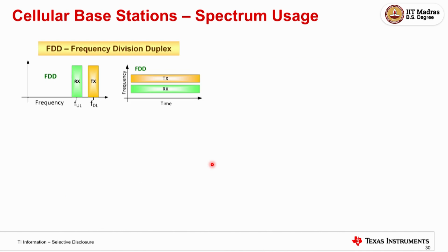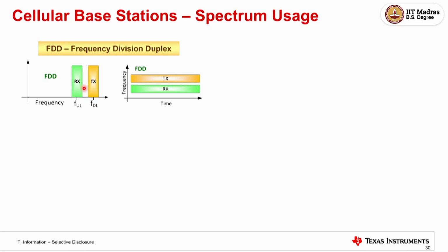Okay. So two common modes of communication are there: one is FDD and the other TDD. I said transmit and receive have to coexist, so there are two ways of doing it. One is you split the frequency, the transmit frequency is slightly shifted, the receive frequency is slightly shifted. You frequency duplex that when you are doing a communication, or you do it in time slots.